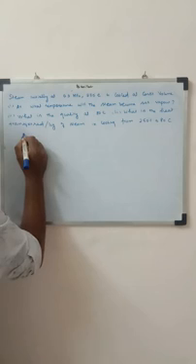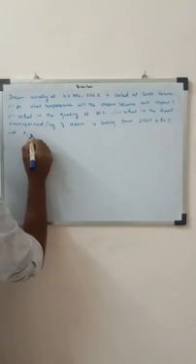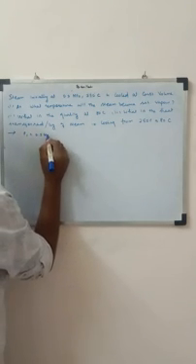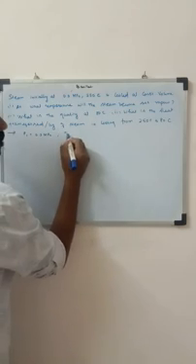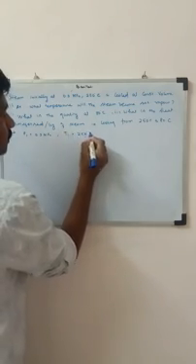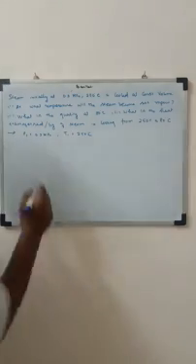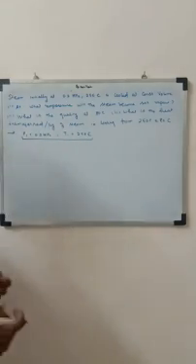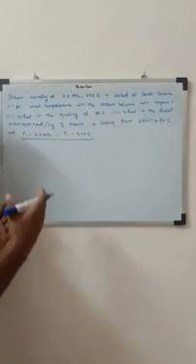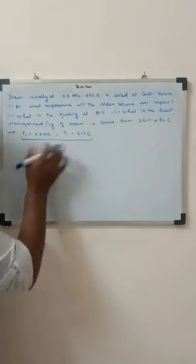So we start with pressure P1 equal to 0.3 megapascal, and the temperature T1 is equal to 250 degrees. First we need to find out which state this particular state is in. Whether it is in a subcooled region, or in the mixed region, or in the superheated region.